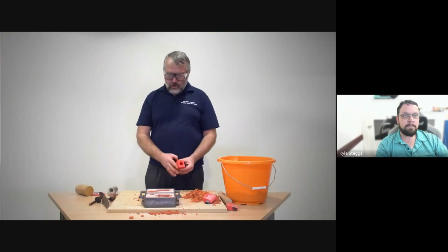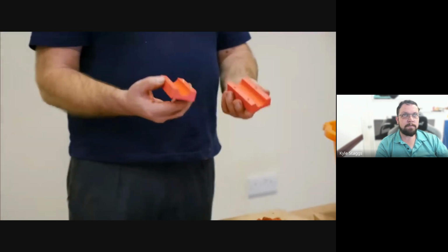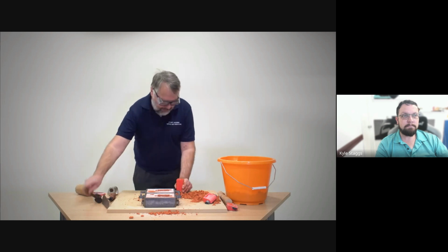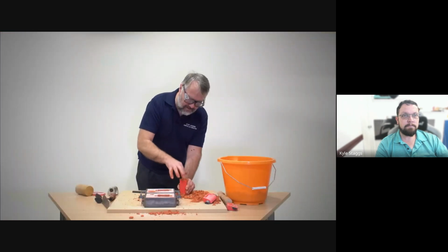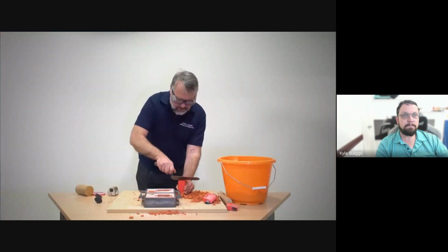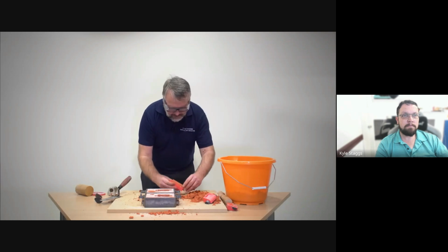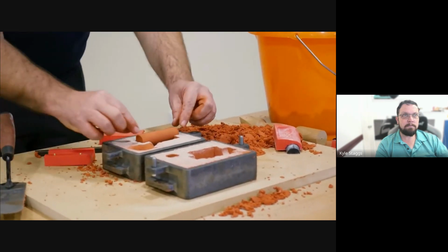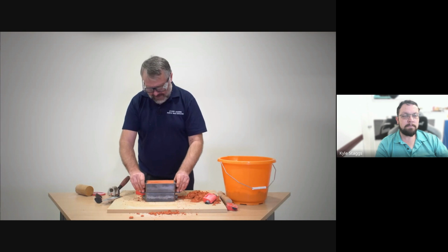We just need to produce the core to lay across so that we can form the hole through the middle of the casting. We use the two-part block, introduce sand, poke it down and ram it to give it some strength. Make sure it's full, trim the top, and then by giving it a tap, it should release the core, which you can carefully lay across the prints. The two halves go together, again just checking for loose sand, locate a pin, put it together, and that's ready for pouring.